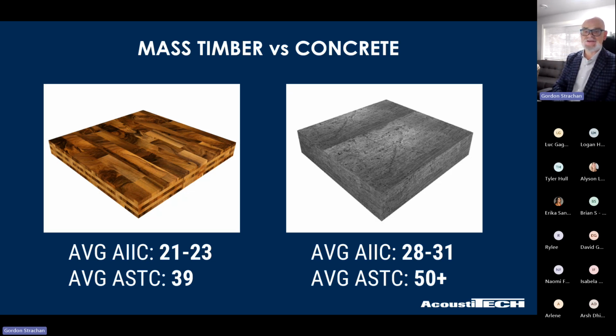So what we're looking at here is where they start. So we know, as we mentioned before, concrete is good with STC, right? That sound transmission, it is always going to achieve more than 50. I don't care if you got a 6-inch slab, it's going to do it. It's going to get you better than 50. So there's no reason to deal with anything else other than IIC on that concrete structure. And as we showed you before, you can literally do that with one solution. One piece can do it all.